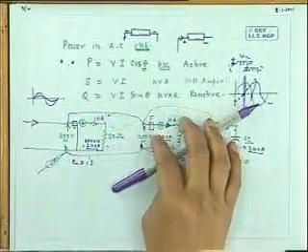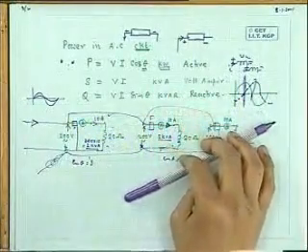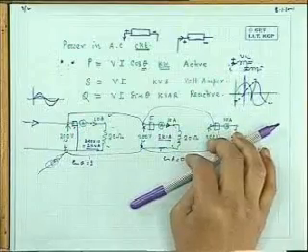The magnitude of the current to be delivered by your generator or your overhead lines will be decided by the sum of the currents. How much current your overhead conductor will carry is not decided by how many kilowatts one is consuming. It depends upon the amperage, how many amperes you are taking. Therefore, the size of the conductors will be larger.